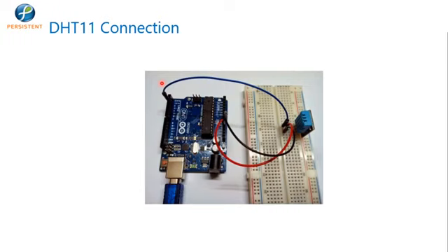So, here we go. The DHT11 sensor would look something like this. Again, this sensor also will have 3 connections: 5 volt, ground and another data pin. The data pin, you can take on any one digital pin, let us say pin number 2, and the remaining are connected to ground and 5 volt. Let us have a look at the code and the output on the Arduino board.